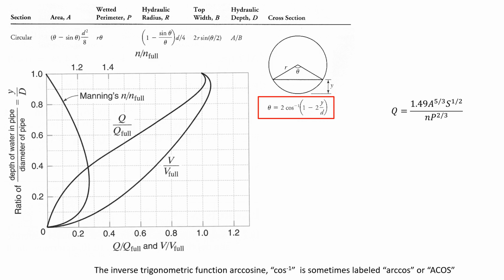All right, exactly right. So when it's 95% full, if you take it up the rest of the way, you're just getting a little bit of flow area, but you're getting a lot of wetted perimeter. And so you're better off not getting that extra flow area and avoiding the additional friction, because think about it, when the water's not quite touching the top, no resistance on that entire length. But as soon as it goes to the top, it's about the same length, but now it has resistance. So it's kind of an interesting thing. This figure's capturing the fact that you actually have better flow performance when it's almost full than you do when it's all the way full.